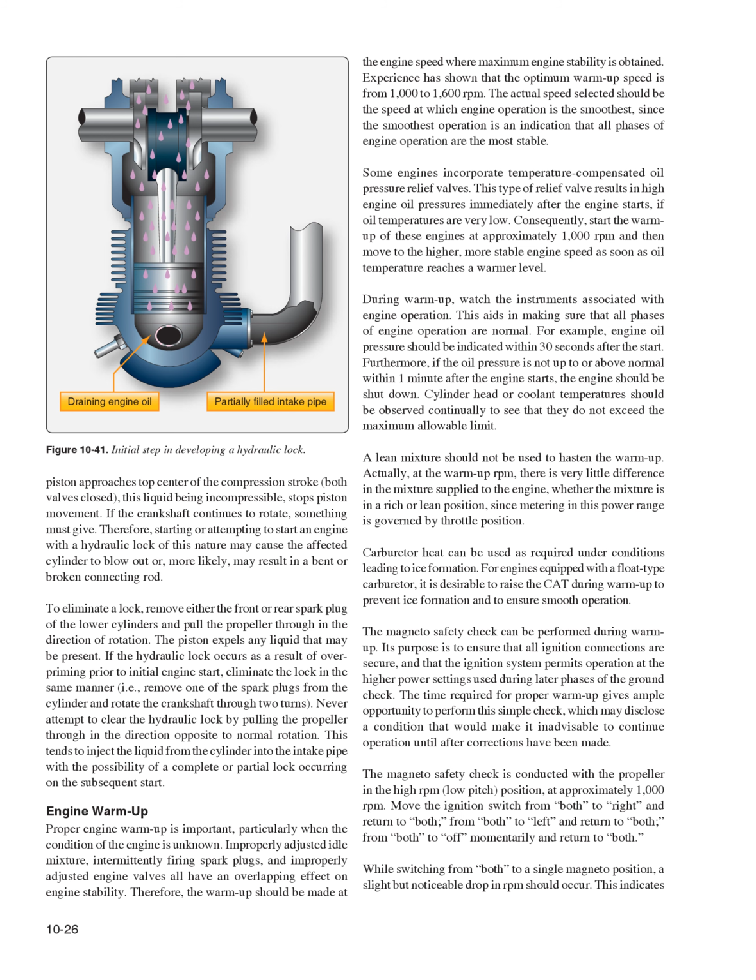During warm-up, watch the instruments associated with engine operation. This aids in making sure that all phases of engine operation are normal. For example, engine oil pressure should be indicated within 30 seconds after the start. Furthermore, if the oil pressure is not up to or above normal within 1 minute after the engine starts, the engine should be shut down.